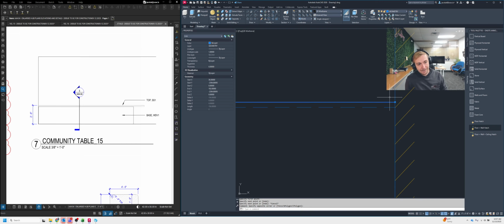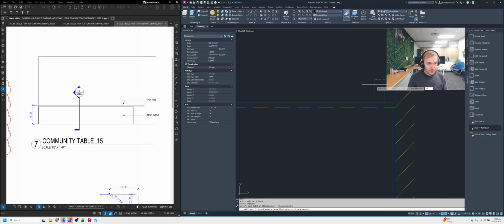So when I do that, I need to draw in an imaginary line temporarily that's 3/4 inches wide. Again, just checking that: 3/4 from the wall to the line there. All right. And then in order to do an array path, it's important to remember that you're always going to measure from center of reveal to center of reveal on the opposite side.